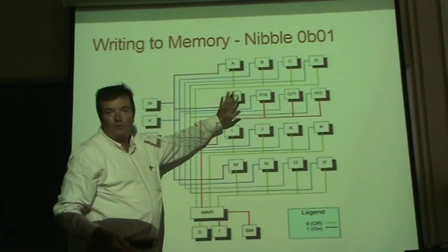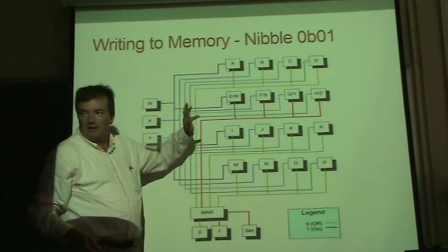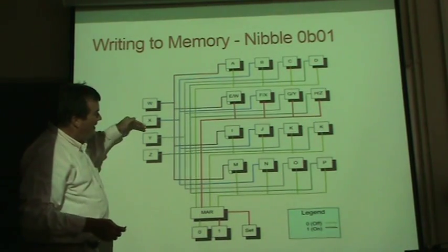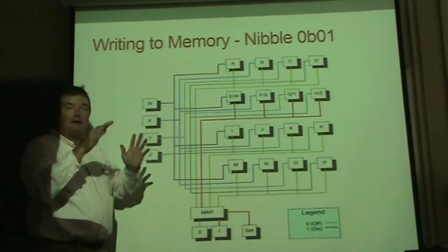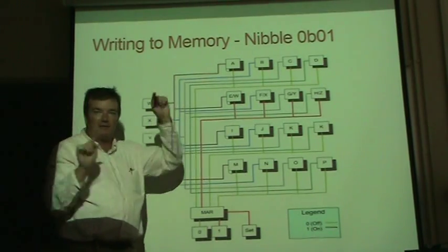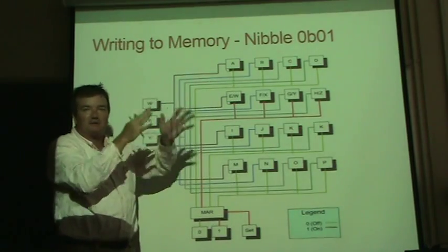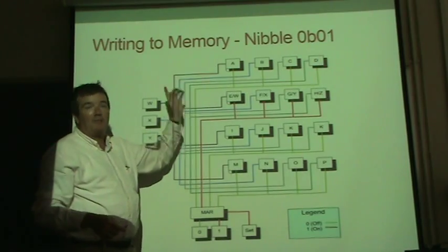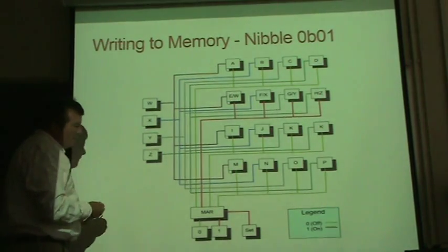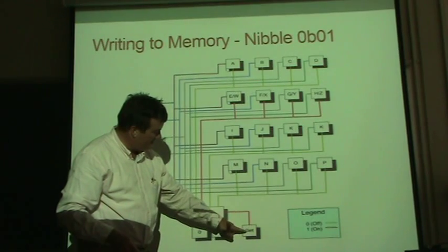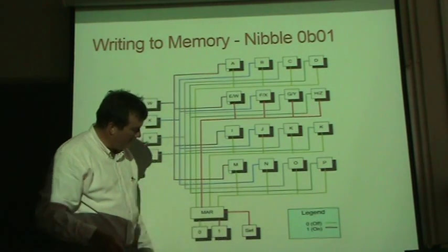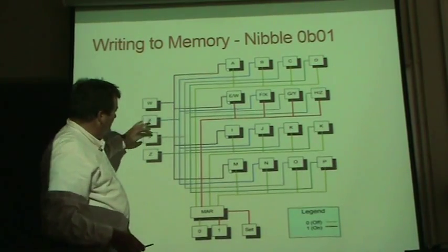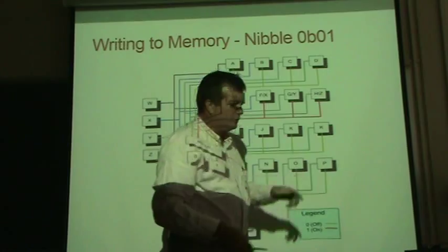Do you know why I put an or, one or the other? Because as soon as you set this, the old values are getting washed away while the new values are coming in. They go through the flip-flops, and it takes a little time. So there's going to be a little gray area where it might be the old value, it might be the new one coming in. But then, once we turn this to 0, it'll shut off all of these, and then the new values, the W, X, Y, and Z, will appear here. So once we shut that off,